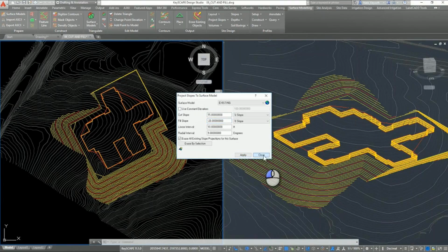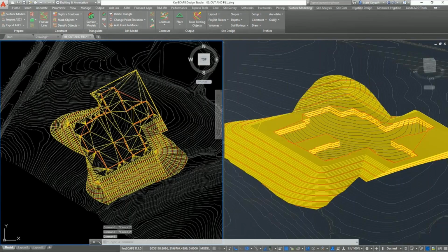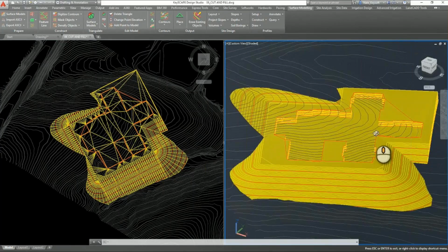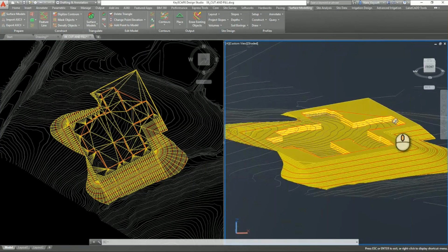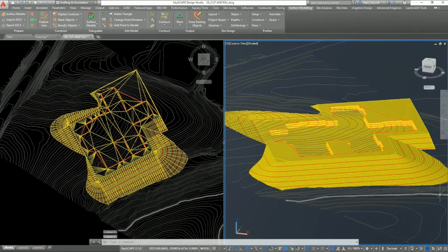We've already identified that on the north side of the site, the slopes were taking us out of the boundary of the site, so we put in a retaining wall there. We knew we'd need that. You can see based on the existing contours that we're cutting uphill or filling downhill. But what would be handy to know is how we can quantify that.